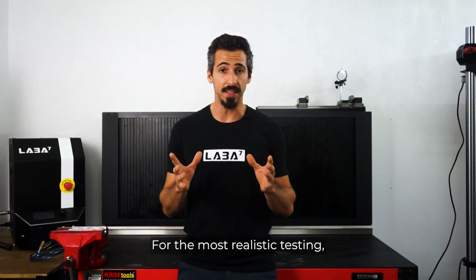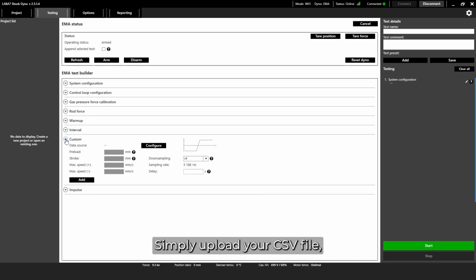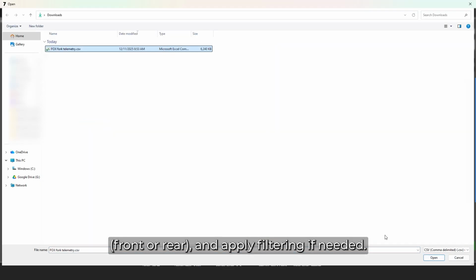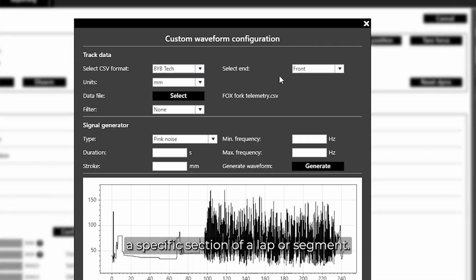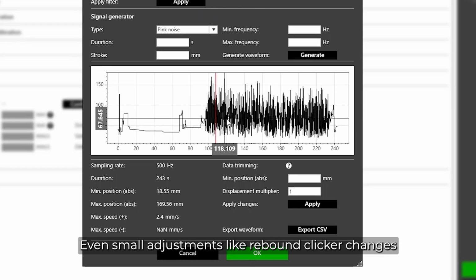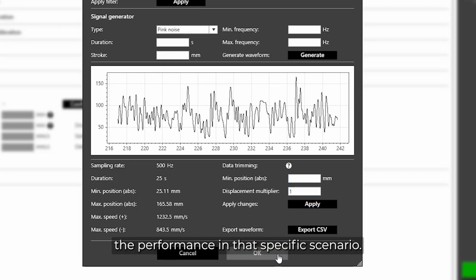For the most realistic testing, you can import real-world telemetry from a race car, motorcycle, or mountain bike. Simply upload your CSV file, select the unit format and the damper position, front or rear, and apply filtering if needed. You can also trim the dataset to focus on a specific section of a lap or segment. This allows you to recreate real track conditions, like cornering loads, whoops, and braking bumps, on the dyno in a controlled, repeatable way. Even small adjustments like rebound clicker changes can be tested against actual motion to see if they improve or worsen performance in that specific scenario.